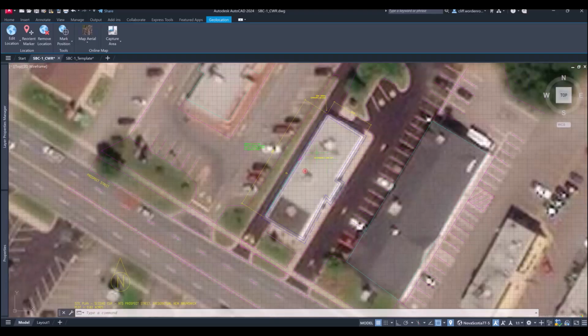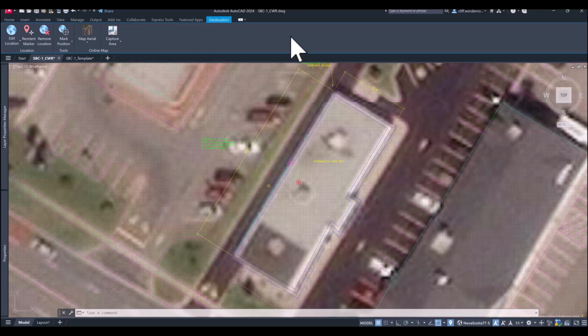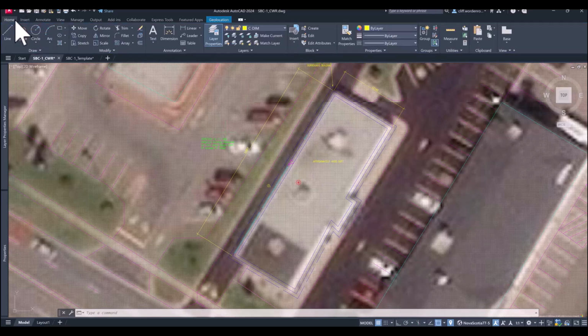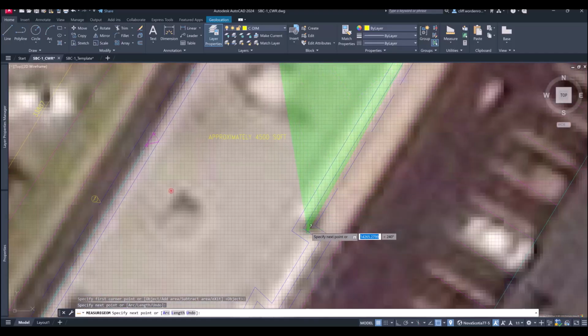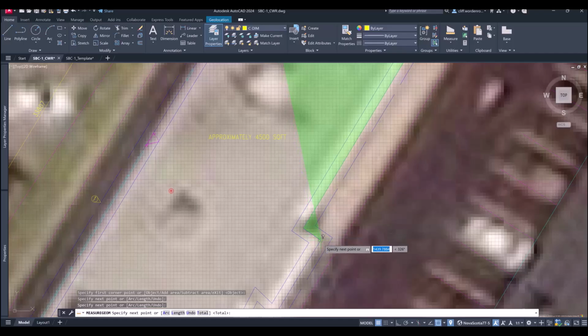You also need the total area of your building. Getting the total area, I'm just going to scroll up here and show you how to do that. If you come over here under the Home tab, underneath Measure, you can grab your area. You're just going to snap this and get your general interior space. It's not the roof line I want, it's the interior of the building itself.